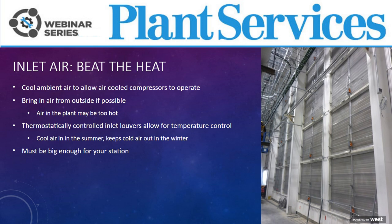So we've already established that air-cooled compressors need cool ambient air in order to operate efficiently. The compressor is going to need cool air for that summer operation, and you want that air to be as clean as possible. Using a thermostatically controlled inlet louver damper like in the picture at right is going to allow you to regulate how much of this air enters the compressor room. When coupled with recirculation, this is going to provide a degree of control over the temperature in the compressor room, helping you keep it cool in the summer months and warm in the winter.